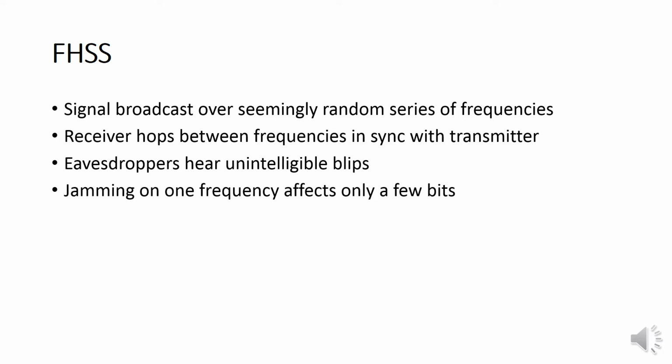The jumping on one frequency affects only a few bits. The selection of the frequency slot in each signaling interval is made pseudo randomly according to the output of a PN generator.